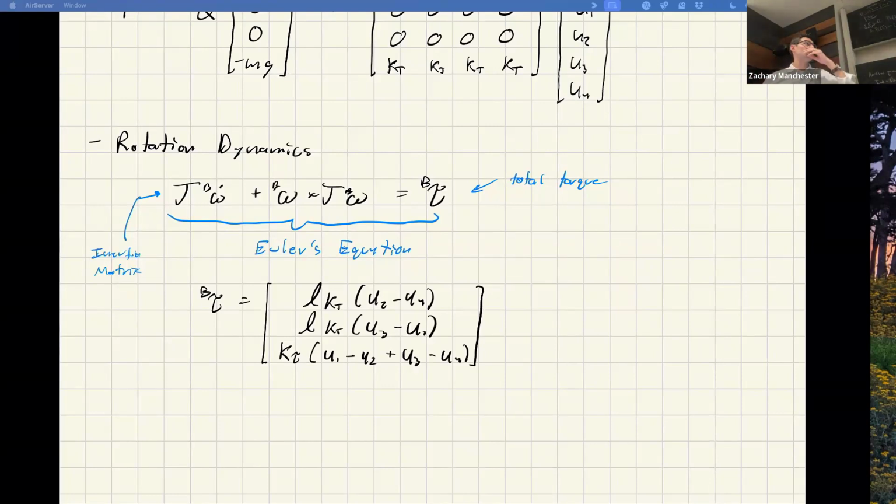They're now using learned residual models with neural networks, like these ones where they're flying through the gates and trying to do really aggressive minimum time stuff. There, you really need super dialed models. So they're basically taking pretty high fidelity models, with legit propeller models and legit aero models, as a baseline. And then they're flying around a whole bunch, taking the residuals and fitting a neural network to them, adding an extra residual term to capture even more aerodynamic effects that they're missing in the first principles models. So you can get really deep on this.